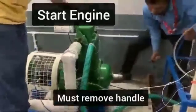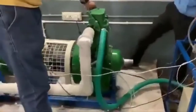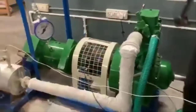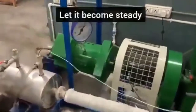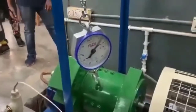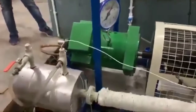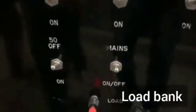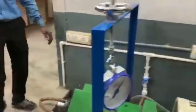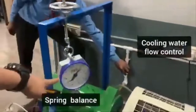Here we are starting the engine. The engine is started and we will let it stabilize. We will achieve a stable RPM, and once the stable RPM is achieved, we will start our experiment. Let it become steady first, and you can see some load is applied over the engine, which is shown on this spring balance. Now here this is the load bank, which is right now in off condition. You can see there is no loading on the engine. The total capacity is 4 kilowatt, and we will apply the load on the engine.